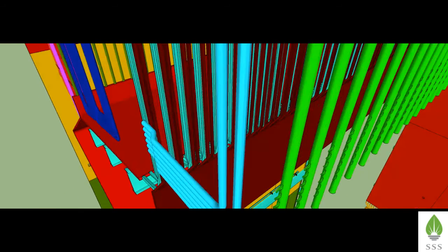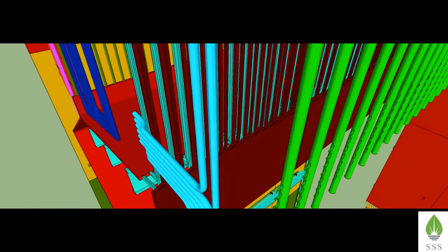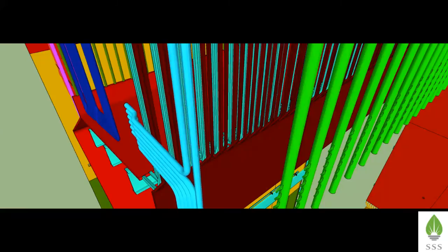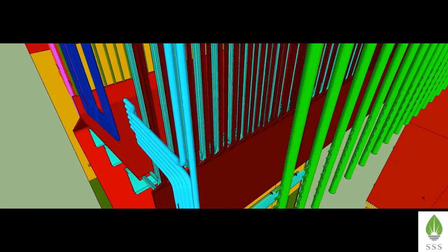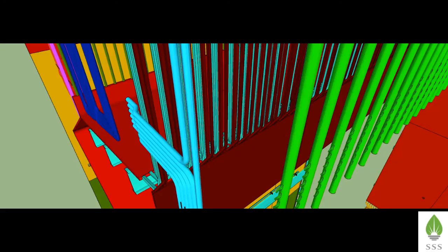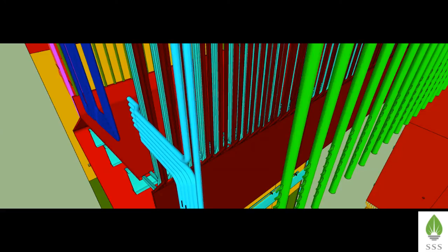The reheater crossover tubes have to be inserted through the gap between the cage front wall tubes and rear screen tubes. So erection methodology, as shown, shall be followed.